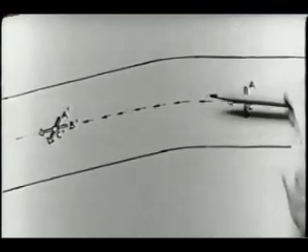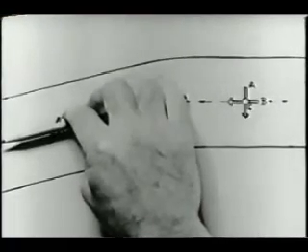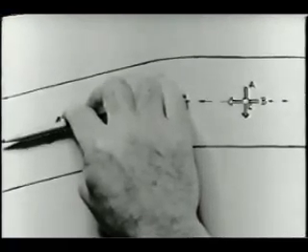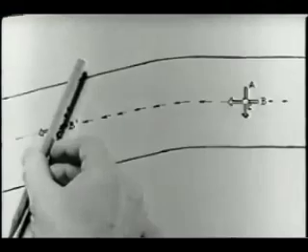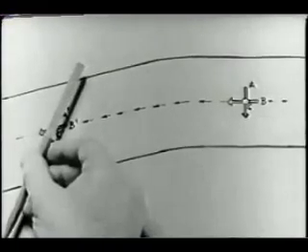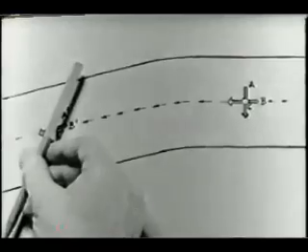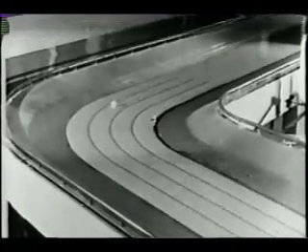Line B follows its streamline and therefore rotates in a counterclockwise sense. Since the vertical vorticity remains 0, line A must rotate clockwise by an equal amount. This clockwise turning of line A into position A prime requires that the velocity at the inside of the bend be greater than the velocity at the outside.